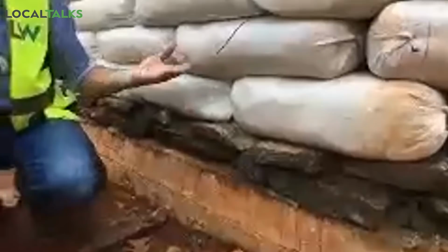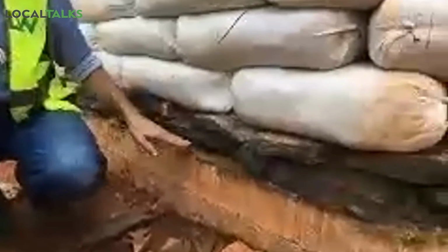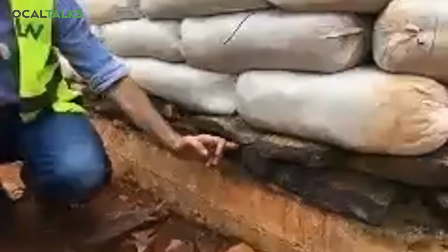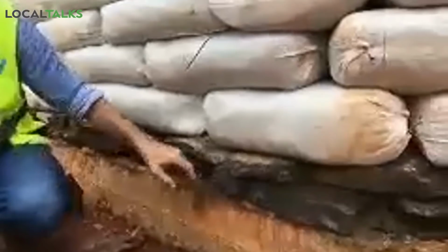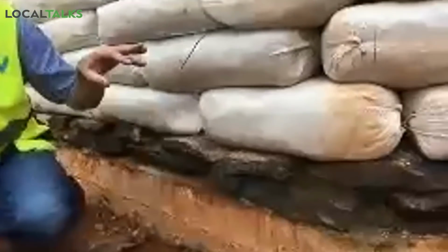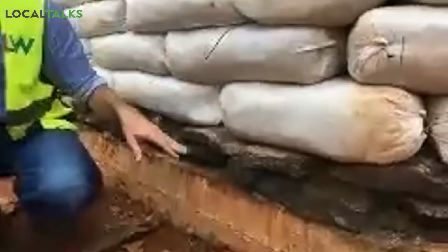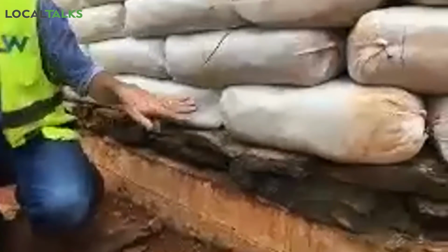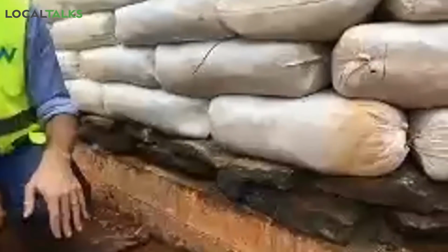We've placed them in a conventional mortar bed, but we left the vertical joints between the stones free of any mortar and instead filled them with sand. Sand obviously also has zero capillary action, and therefore we are completely sure that on a triple layer we have avoided any risk of moisture moving up the wall.